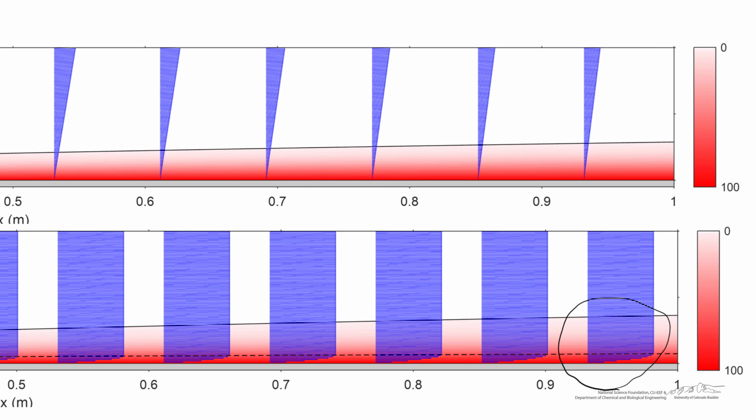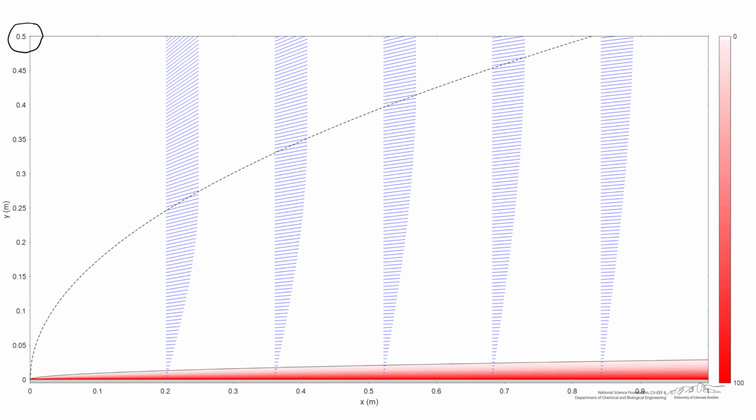In contrast, oil has a Prandtl number on the order of 10,000, and what we see is a very large impact on the velocity profile and a relatively small difference in temperature. So the thickness of the thermal boundary layer is small, and the thickness of the momentum boundary layer is gigantic. In fact, if we scale out quite a bit, here I've got a vertical axis of 0.5 meters instead of 0.1, which was the original vertical axis, and you can see just how much larger the momentum boundary layer is than the thermal boundary layer.